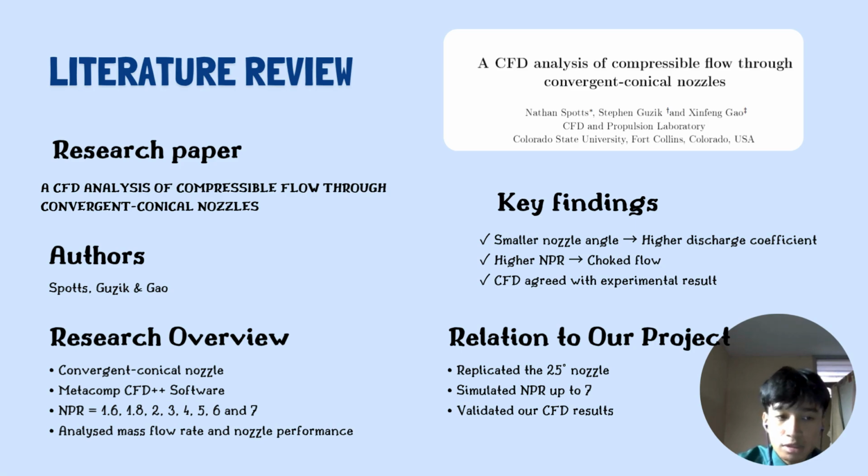The study evaluated important performance parameters such as mass flow rate, discharge coefficient, thrust coefficient, and flow behavior inside the nozzle. The results show that smaller nozzle cone angles produce higher discharge coefficients, while increasing the nozzle pressure ratio accelerated the flow until choked flow occurred. The CFD predictions also show good agreement with the experimental data, demonstrating that CFD is a reliable method for